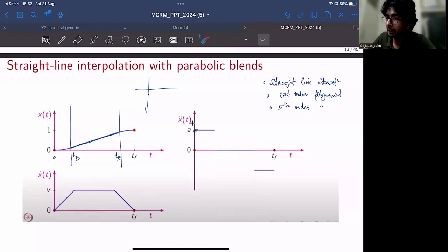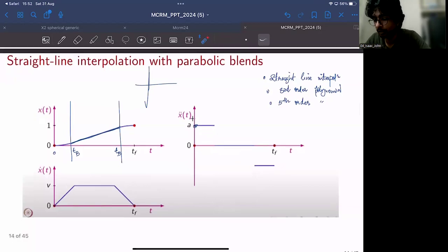If you implement that on the controller, it will command the motors and actuators to increase the gain as much as possible. It could be beyond its capability, and finally it'll die off. No system can reach infinite acceleration, because before that, the system will fail.